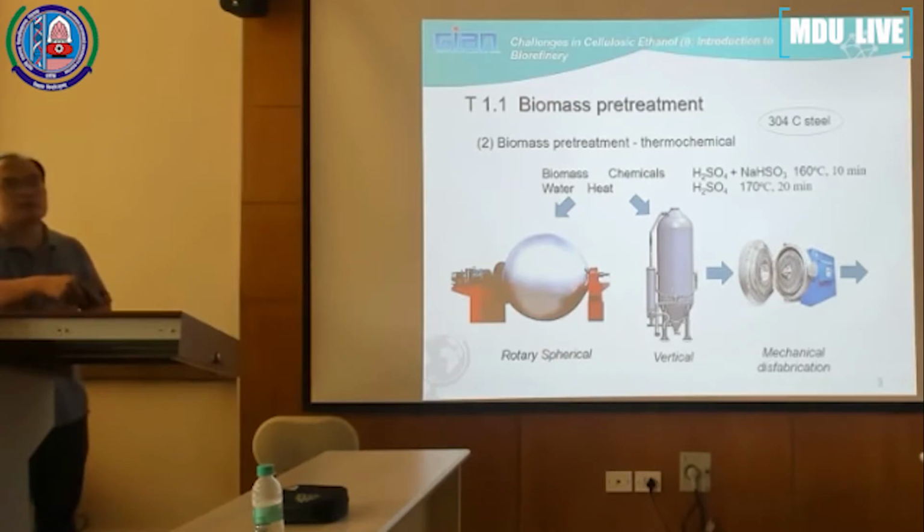For each cycle, the liquor is separated from the solids, recycled from bottom to up, and passed through the heat exchanger. The liquor is heated here and circulating. Then the mass transport is better. But this one does not need a heat exchanger. It rotates to realize mass transport.